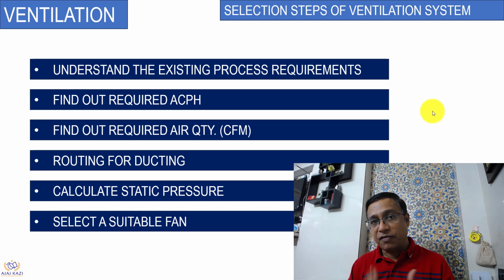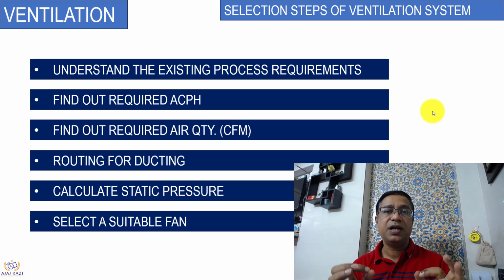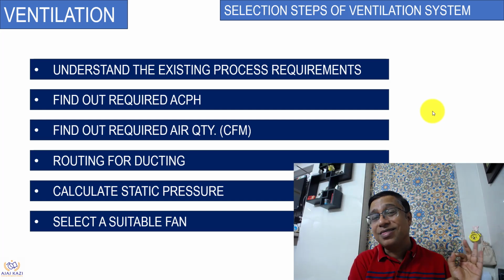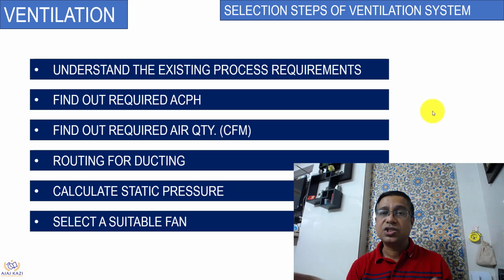There are different types of fans. We are going to see it. You need to select a right fan, right? When it comes to smoke or fire, the fan has to be rated for that fire, for that temperature. You can't just select this normal fan. The fan will get melted and you will have trouble.